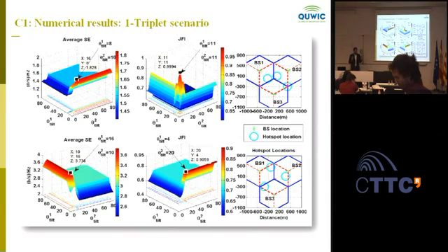But if you want an advanced answer, beamforming in general plays with the azimuth of the antenna, but this solution is about the tilt of the antenna. Even if you have a beamforming solution, you can still implement this solution because it will keep the tilt optimal all the time. Getting my point?